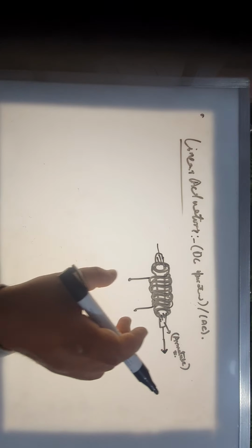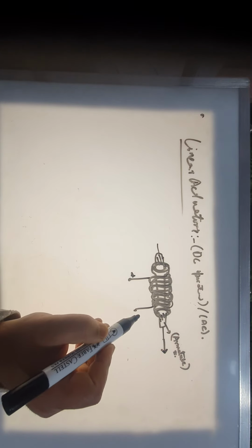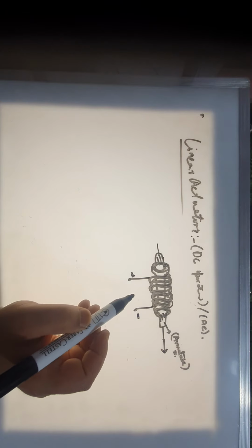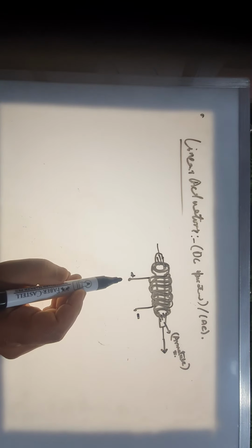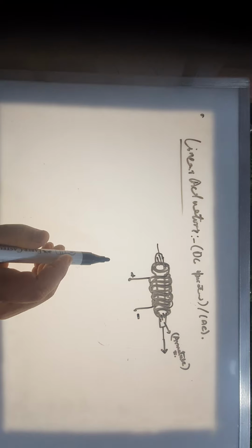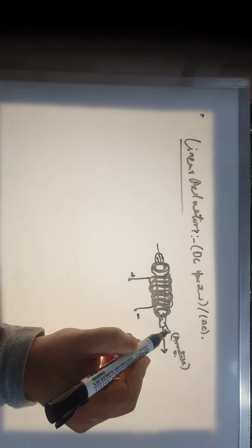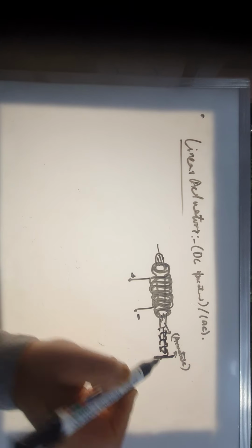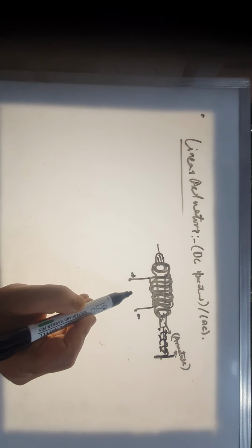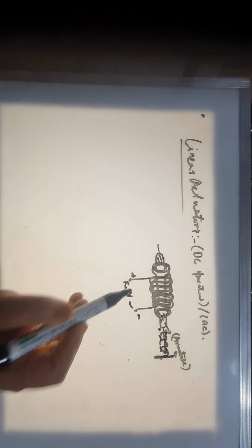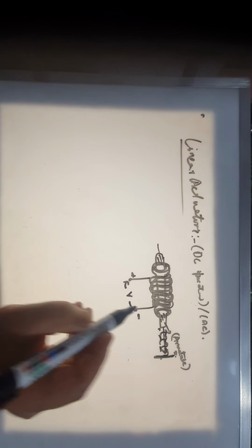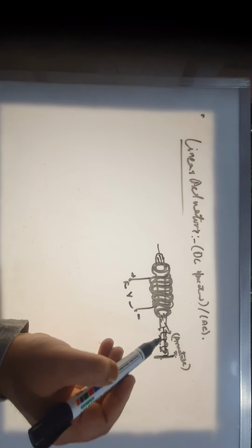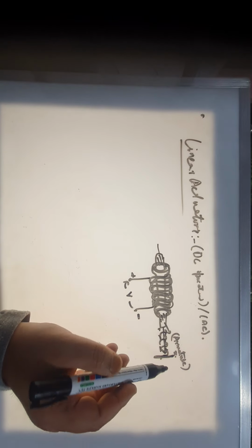So if we simply give the voltage here, this armature will be thrown out. So you use a mechanical system to constrain its motion, and in order to bring it back you normally use a spring. So you put a spring on this side. Whenever you put a designated voltage, the voltage that we have to provide depends on the force that this plunger has to provide to the spring.